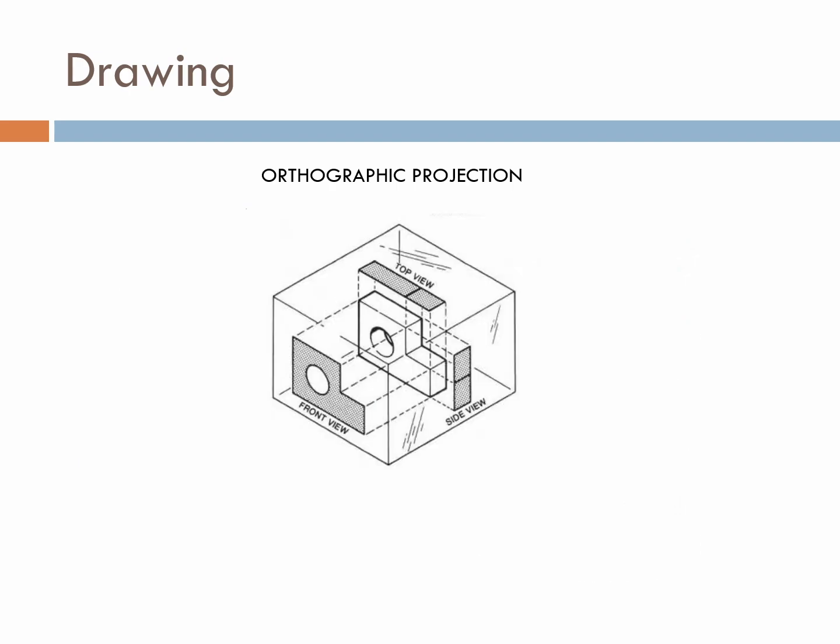Okay, here again, we see the front view, which is this right here, the side view, which is this here and that there, and you have your top view, which is that and that. And that's all you see. Now, you would have some hidden lines in there because you have that hole in there. So you'd have hidden lines in here too, but don't worry about that right at the moment. But that's the basic concept of third angle orthographic projection.